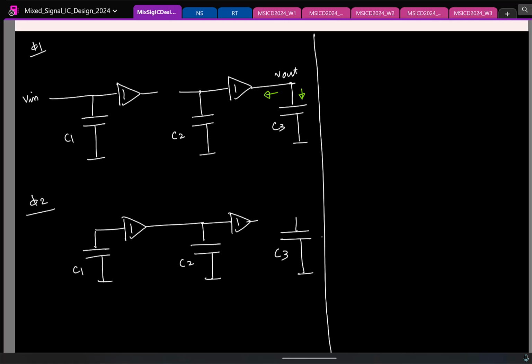The op amp, it's an ideal VCVS buffer. It can provide any amount of current. That is also an unknown to you, right? So again, this is like KCL, right? If you want to find this voltage, this is a buffer. What is this voltage equal to? Same as this guy, right? So let me call it, I don't know, V2 maybe. So from this, it's clear for me that V out of n is equal to V2 of n. That much is clear. So again, remember, whenever you have the output of an op amp or a buffer like this, there is no point in applying KCL or charge conservation there, because you will end up with an additional unknown. Okay.